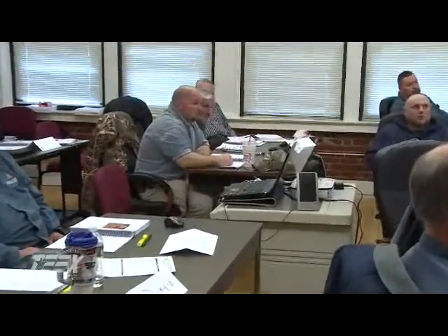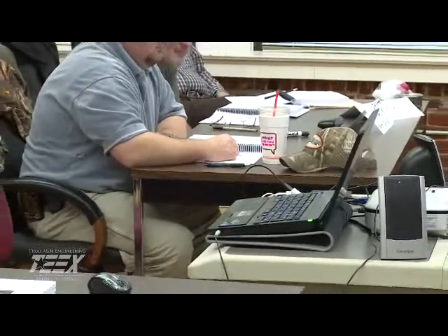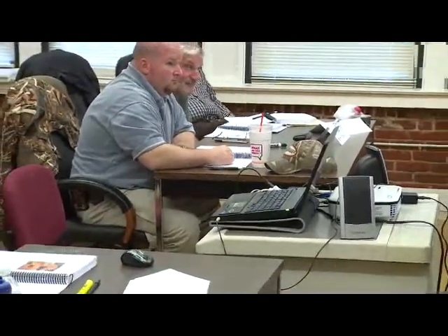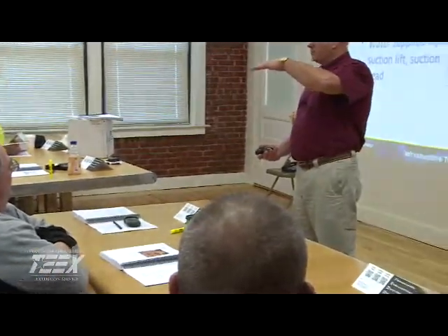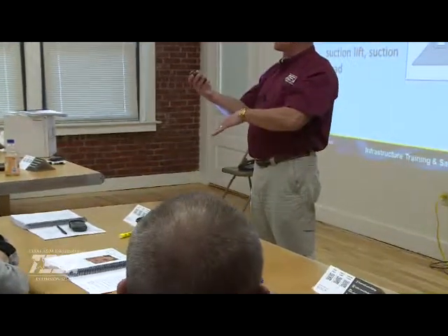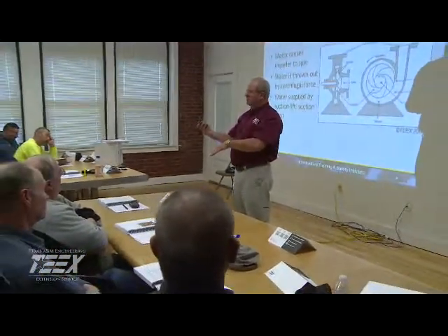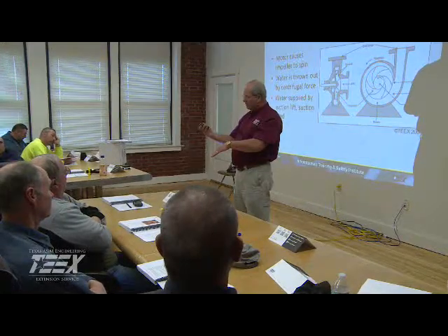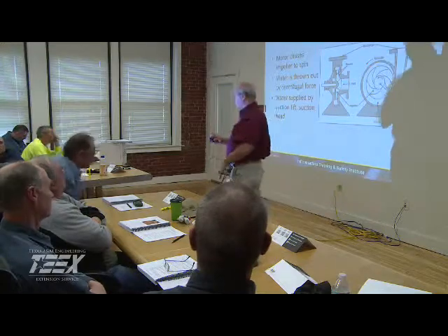Now, pushing down on the Earth's surface is 14.7 psi. If you take 2.31 feet per psi, multiply it by 14.7, you come up with approximately 34 foot. So 34 foot of water is equal to 1 atmosphere of air. A perfect vacuum, you could get 34 foot of lift. Impossible. Friction, and when water is dynamic, it starts to vaporize in motion. So basically you can get 23 to 25 foot of lift, okay?